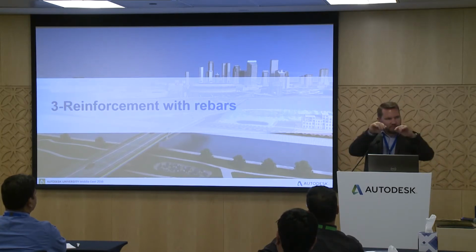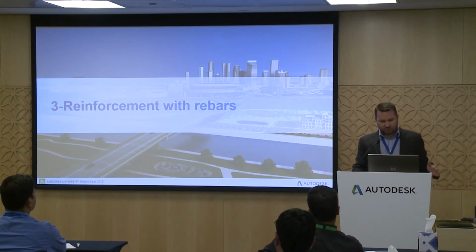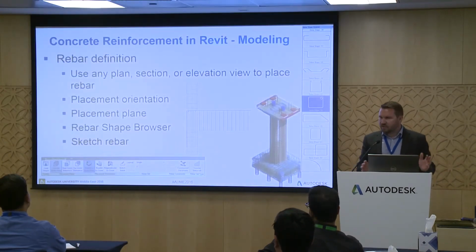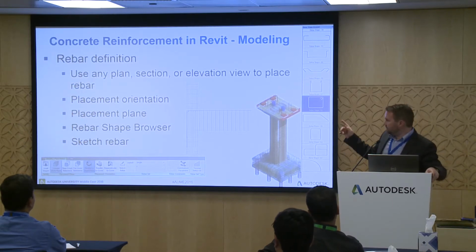And so when you put reinforcement even manually, you can display the theoretical reinforcement needed and what you put really in place. So it's another method than doing it on paper. The drafter explains what you want. Or it can be something in addition to check for you and your drafter. So when after you want to draw your own reinforcement, you can now use, for 2 versions, any plan, any section, elevation, or rebar. So it was not the case before.